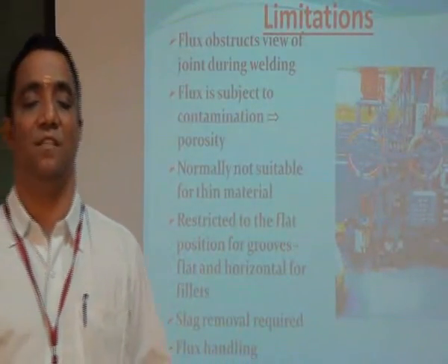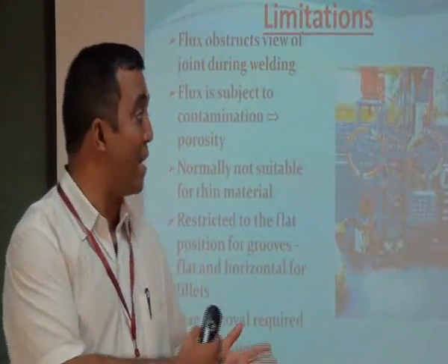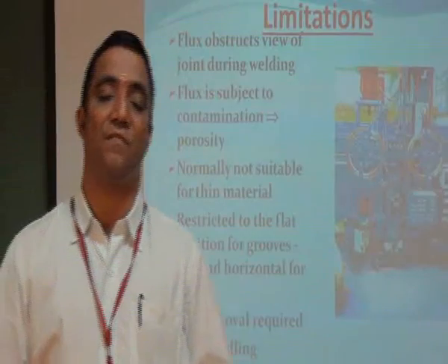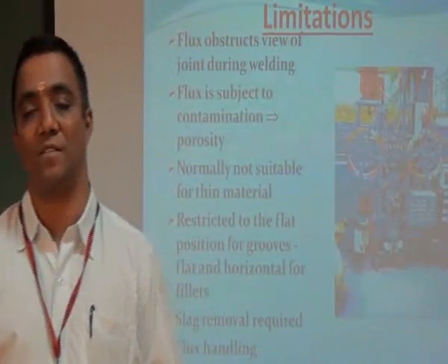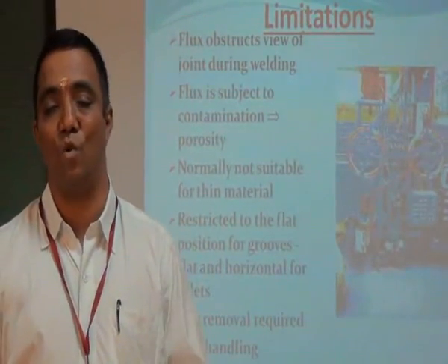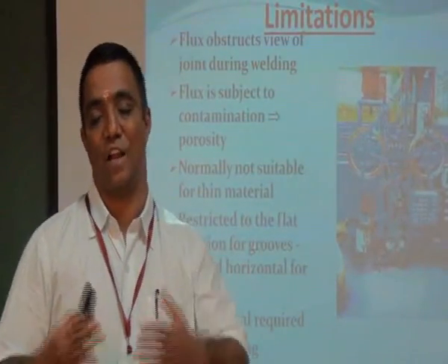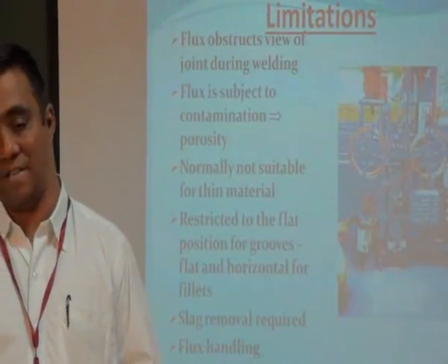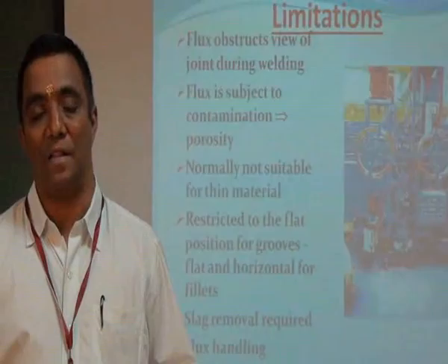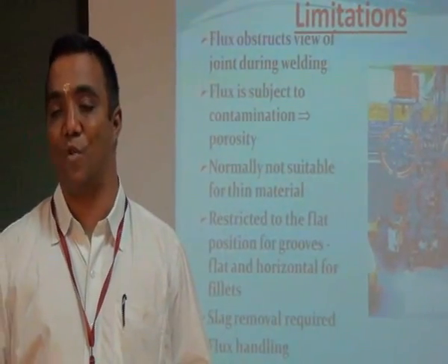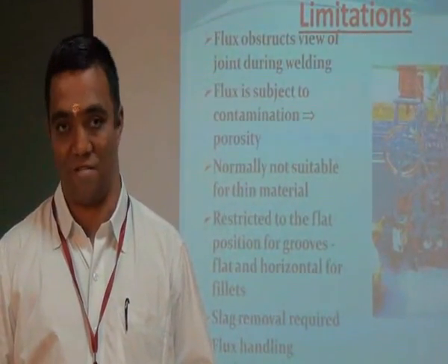And then the last, the submerged arc welding process, is an automatic process. The welder does not have any control over the arc. It is a high energy process, and it can be used only for thicker plates. And remember, the shielded and the submerged arc welding processes cannot be used for repair welding at any cost.